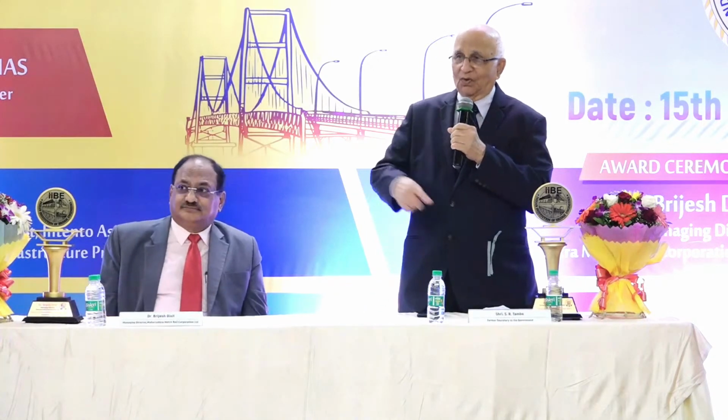And as soon as we took it over, I said, let us go and inspect it and see what needs to be done. As we were traveling, I was getting down at every bridge and CD work and inspecting. At one bridge, it was a slab bridge, all rocky foundations. I found that there was a hole on one side of one pier, a deep hole. And then I saw that it's pretty deep. So I said, let us see what is wrong with this. Actually, that pier was acting like a lintel on that big hole.